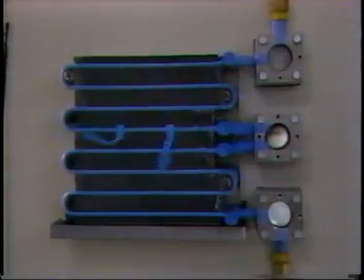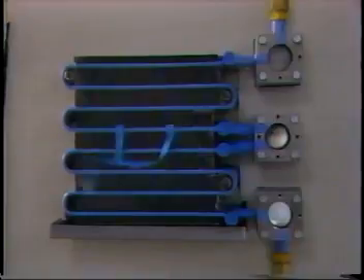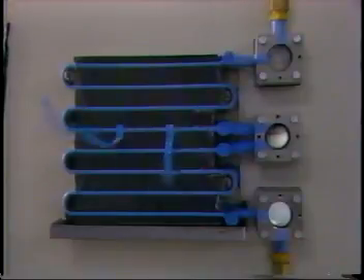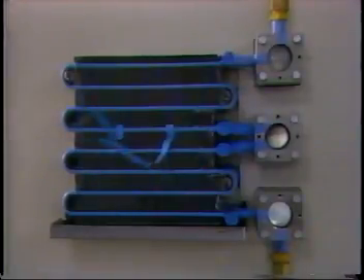In other words, the amount of refrigerant is so much that it cannot evaporate completely before it leaves the evaporator. This means that the refrigerant is not taking enough heat from the air, similar to a condition when there is insufficient refrigerant. These experiments show that the air conditioner's cooling capacity is affected if the amount of refrigerant is either not enough or is too much.